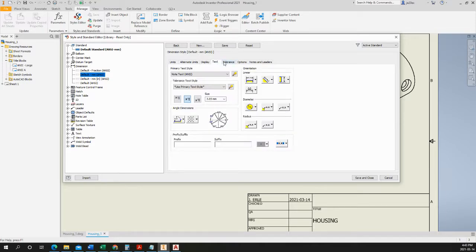One thing I like to change, and it's a personal preference for me, is the vertical dimensions. When I do a vertical dimension, I want the text to remain horizontal, like along with all the other text that's on that page. For example, in the title block, all my horizontal dimensions. So I select this one. So that'll keep the numbers horizontal, and I don't have to turn my head or rotate the piece of paper if I'm looking at it to read what's there.